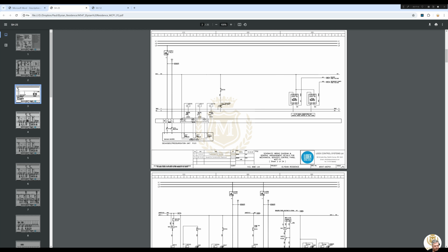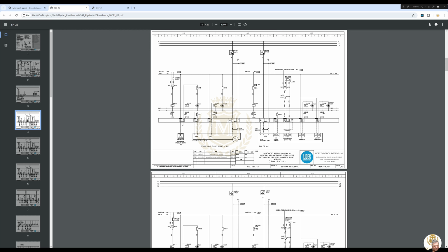Differential degasser PU01. That one is my boilers, shunt pump and boiler 1. We're modulating the boiler 0 to 10. Lockout alarm, enabling the boiler there. External interlock on relay 325. This is a 325, which is your pump. So we're actually checking it all, making sure we get the pump flow before we actually enable the boilers.